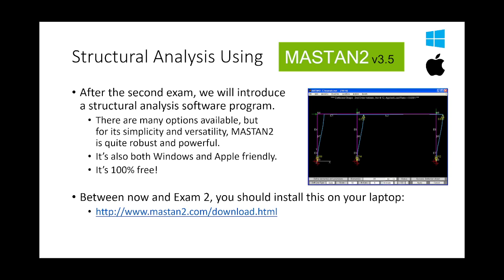You're going to see the iteration involves changing the member sizes, and because your structure is statically determinate, changing the member sizes isn't going to change the forces. But the other reason I want you to use Mastan for the project is, as I mentioned, I have no problem if you tweak the joint locations a little bit.